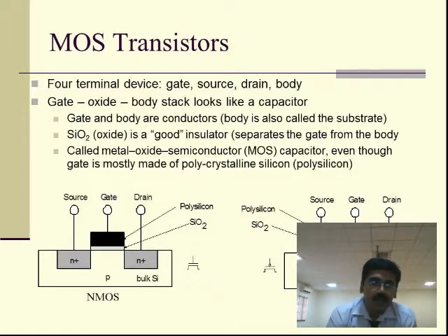Normally in an NMOS transistor we will not have any current conduction when the channel is not formed. In order to form a channel, we need to apply gate voltage. If the gate voltage is greater than the threshold voltage, the channel will be formed. Forming a channel will not lead to current conduction, so we need to make a potential difference between the source and drain regions.